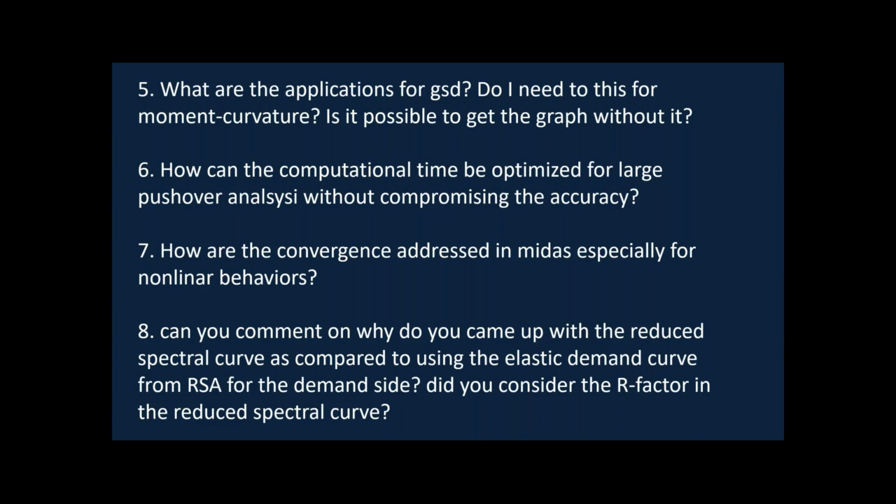So if you are quite confident that there is a very slight change in the axial force that we see in the structure during the pushover analysis, then we can set the structure data to no interaction with the axial force, and in that case the computational time can be reduced. But again, we will compromise on certain accuracy, so a balance is to be maintained in that case.